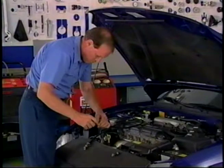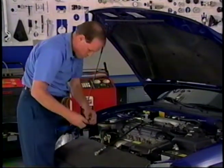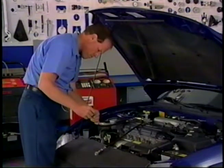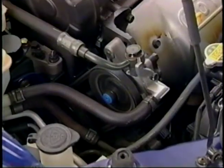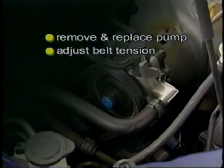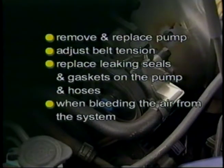Pressure readings significantly above that indicate a system restriction or a bad flow control valve. Pressures below that indicate internal leaks that must be repaired. When working on power steering pumps, follow the procedures in the service manual to remove and replace the pump. Adjust belt tension, replace leaking seals and gaskets on the pump and hoses, and when bleeding the air from the system.